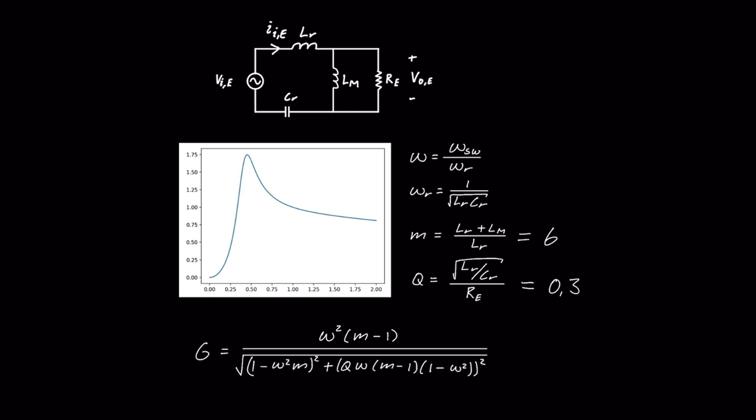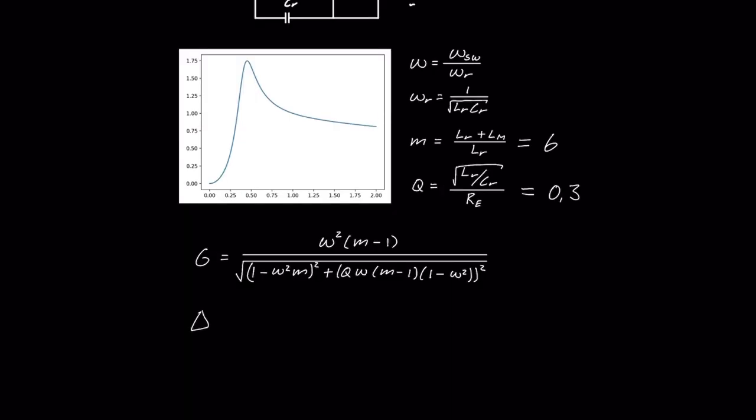So by looking at the voltage gain curve, we can see that by increasing the frequency, gain is decreased. And by decreasing the frequency, we get an increase in gain. So we can therefore say that a change in omega is equal to minus k times the change in gain. So if we have a wanted gain, we can just find the k to calculate the wanted change in frequency. So this k is estimated by a PI controller.